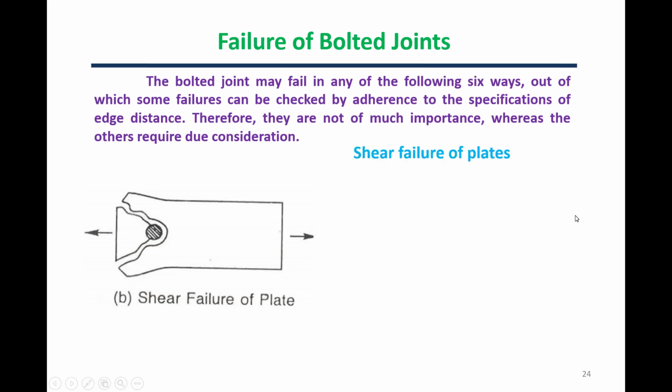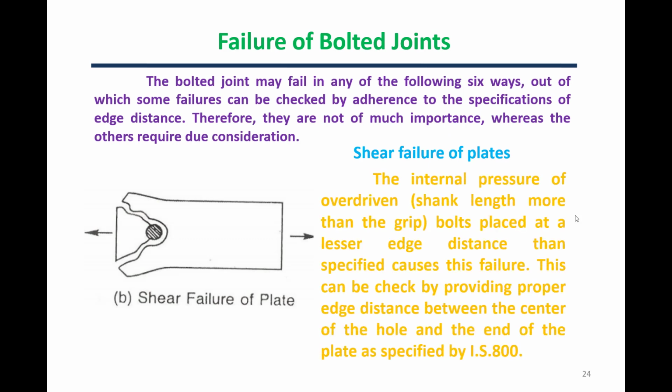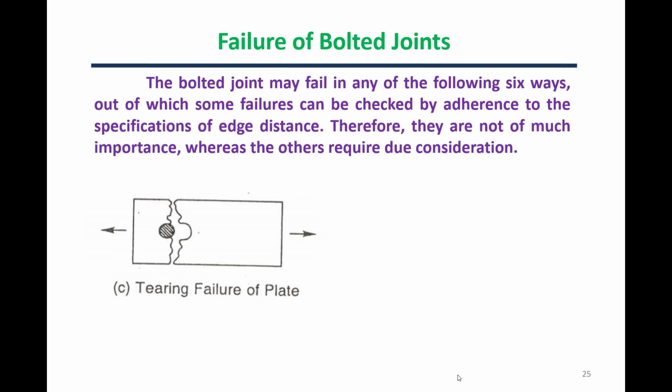Next, we have the shear failure of plates. The bolts placed at a lesser edge distance than specified cause this failure. This can be checked by providing a proper edge distance between the center of the hole and the end of the plate, as specified by IS 800.